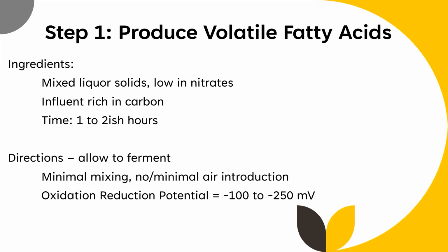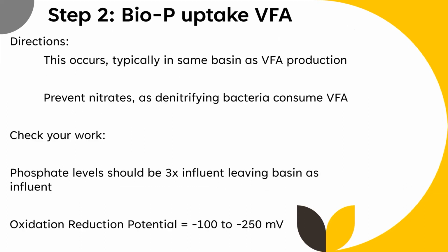Oxidation reduction potential is also key here. If you have the ability to measure it, -100 to about -250 millivolts is the range in which you will see volatile fatty acids produced. The BioP take up VFA, typically in the same basin as where it's being produced.